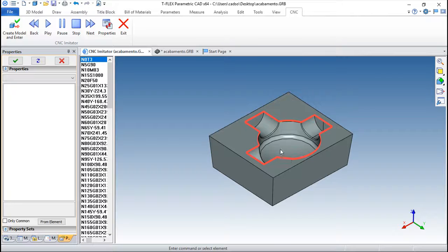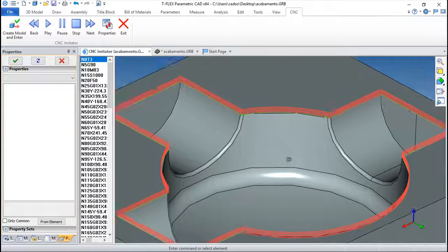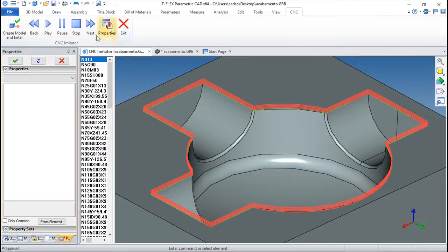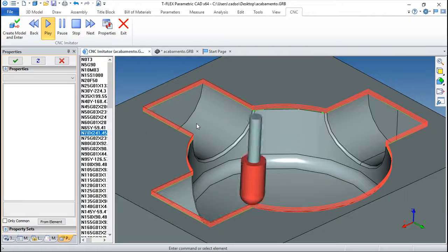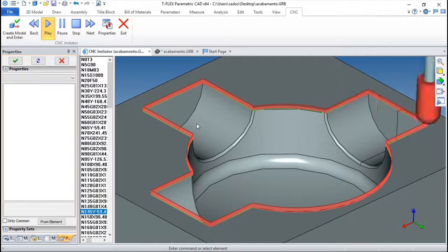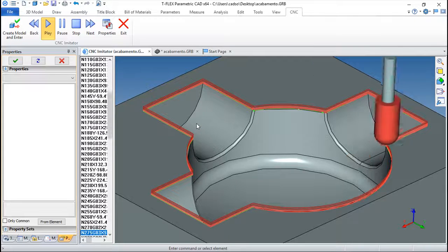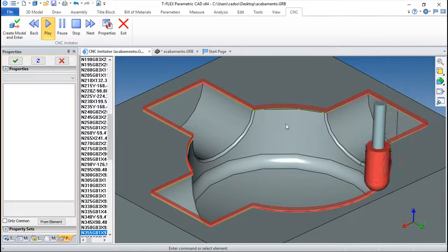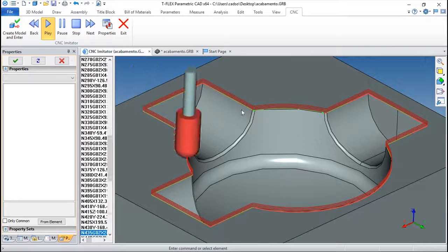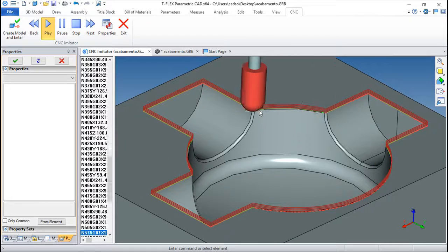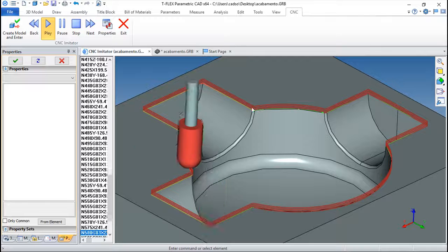see, let us simulate it, it's a kind of stock material that we inform the system, and it will do this in layers. The option of the zigzag, as you can see, will do one pass in one direction and the other one in another direction.